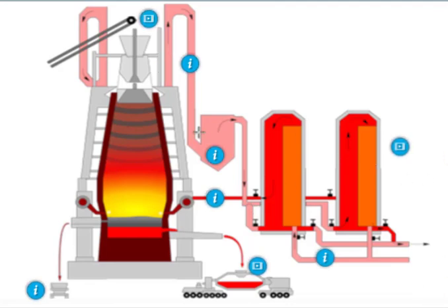Here we call this region the gas cleaning plant, or gas cleaner. We can see it clearly here. The dust catcher, or dust cleaner or cyclone, removes dust from the exhaust gases coming from the blast furnace before they are burned in the hot stove, which uses a combustion chamber. Coarse particles settle down, accumulate, and are dumped into a railroad car, and will be removed by truck or otherwise for disposal.